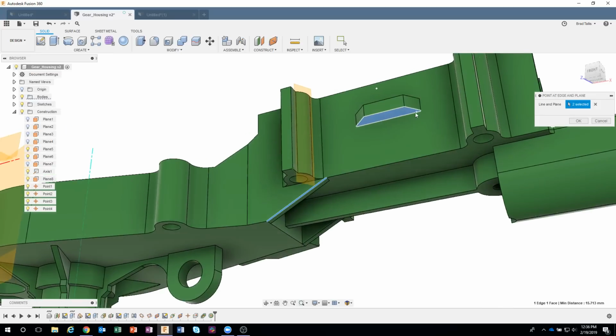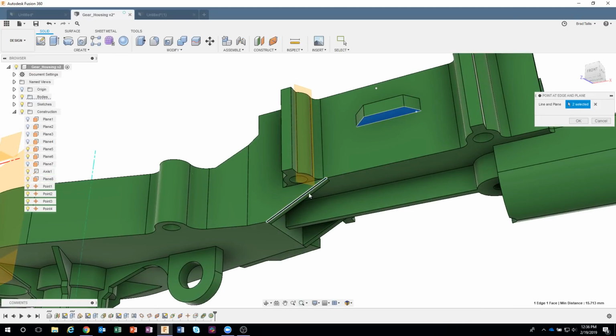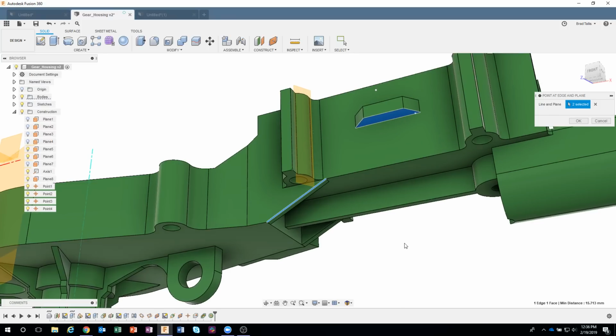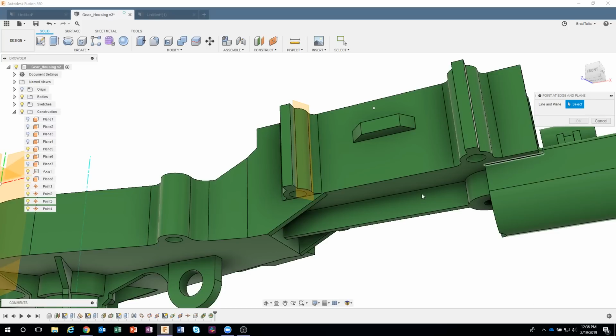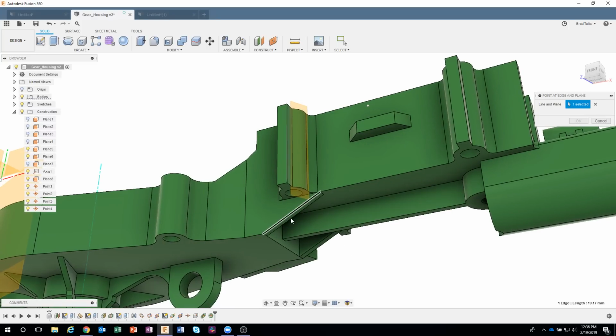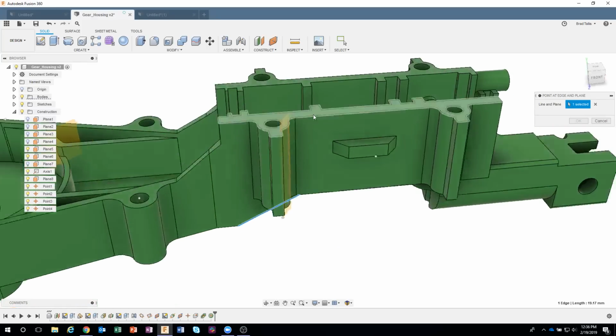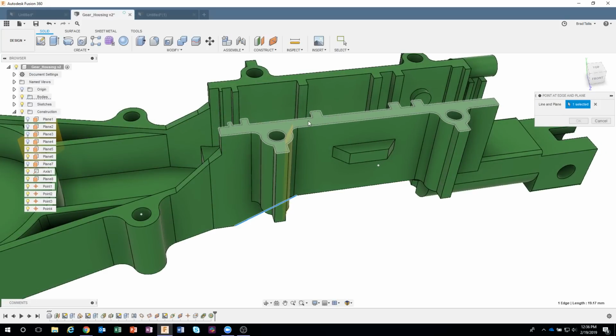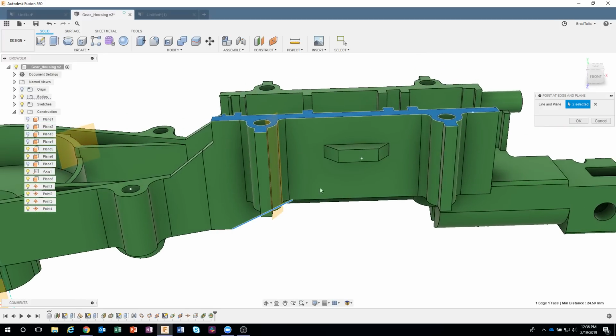And you can see how it created a point that extended up along this line onto that plane. Let me do that again. I'll say this line, and what plane? I'm going to click way over here to the left, and notice it puts the point way over here. So it's basically just extending that line up onto this plane. So that one's kind of useful.